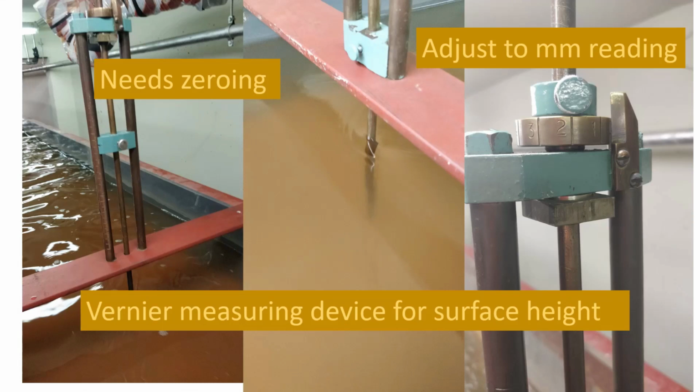We're going to measure depths with these rather old-fashioned vernier scales. They've got a scale on this brass part here. We have to zero them, so we'll put a 0 when it's actually just touching the water surface, but we can get actual fine measurements to the millimeter by adjusting this here. So they are reasonably accurate for measuring down to the millimeter, and no more than that, but we'll see a bit later about accuracy of measuring water surfaces.